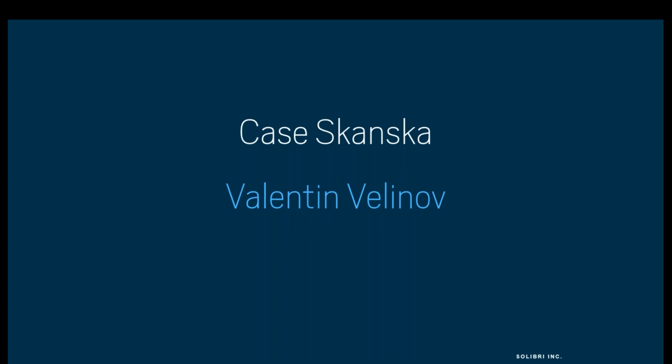I can take a few questions that are for Solibri. So there's a question how to map FI to XML to, let's say, Uniformat or CoClass. I'm not familiar with this FI to XML standard, but if you can create an Excel list of that, you can import it into Solibri classification, which should then automatically convert it to a Uniformat or CoClass.